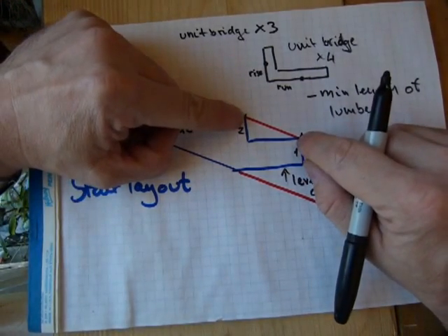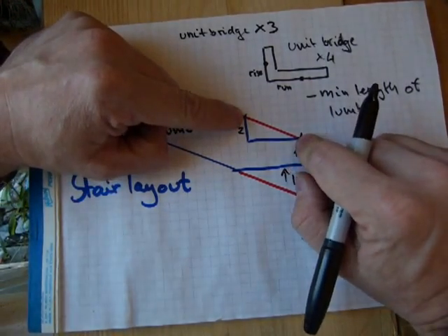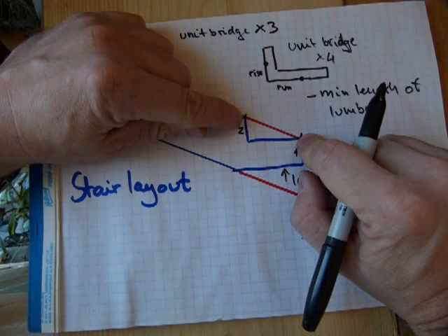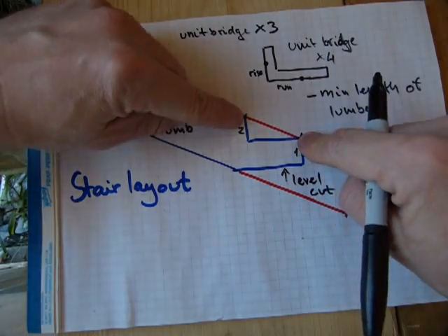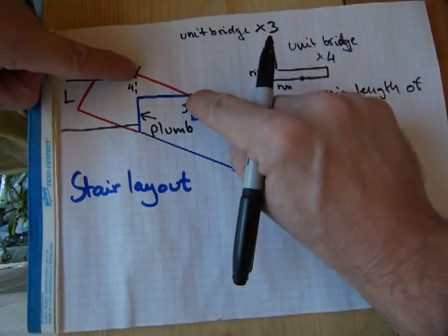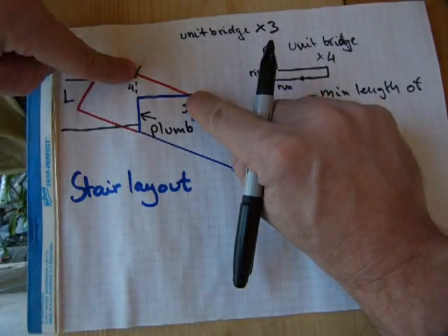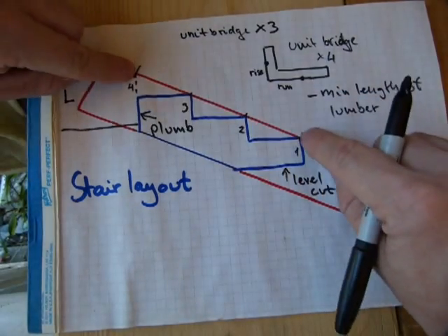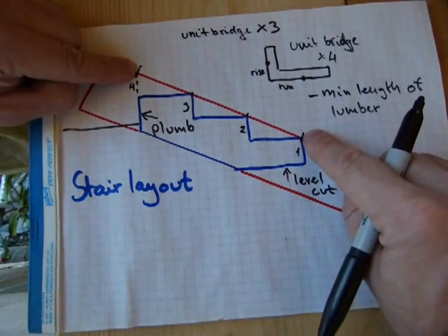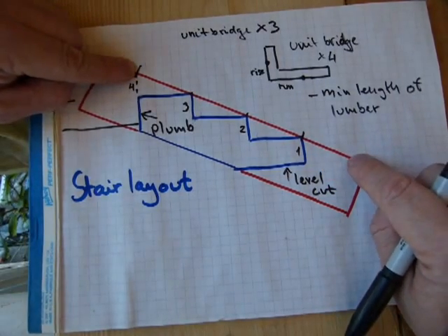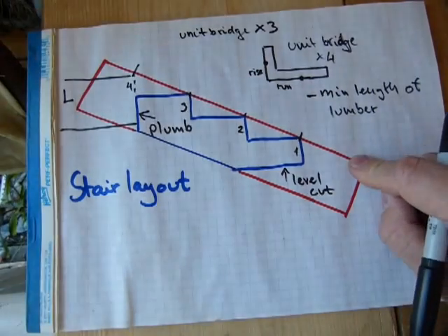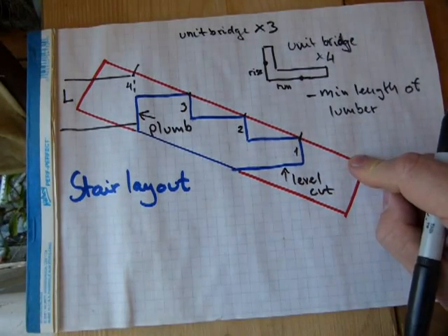The unit bridge was 13 inches and a third, and about the third part, don't worry about it, and don't be looking for it on the tape measure either, but 13 inches and a third, 26 inches and 2/3, 39 inches and 3/3, so that's 40 inches. It was 39 and 7/8, that's almost 40 inches. So we're gonna need an extra 13 inches on top of the 40 inches, so that's gonna be 53 inches.